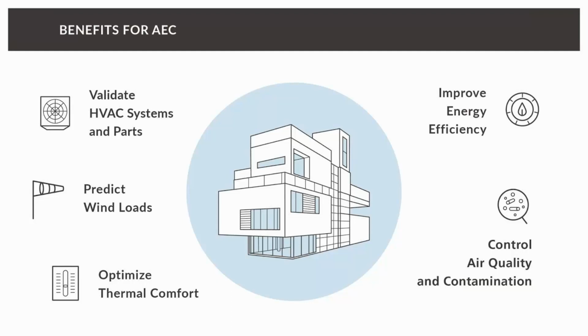And besides smoke protection, this is massively used whenever it comes to thermal comfort and natural ventilation, which can be optimized using CFD simulation. Another thing which is maybe not so important for smoke management, but which is very important when it comes to the facade design, is to predict wind loads for large buildings. There you can use CFD really to get an idea about the forces acting on your building.